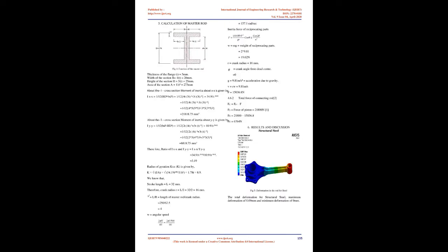3. Methodology. The sequence of methodology is listed below. Problem formulation and identification through literature survey from various ASME journals, Wikipedia and websites collected towards the present research topic. Understanding the working principle of the master rod in radial engine and reasons for its failure. Modeling of master rod of different geometry in CATIA V5 R20. Static structural analysis in ANSYS 14.5 workbench carried out to determine structural strength of the master rod.